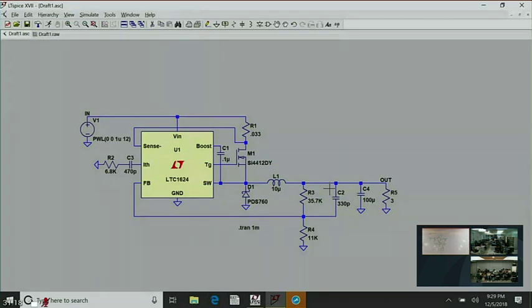Well, the feedback pin voltage is too low by a factor of 3. The output must be too low by a factor of 3. I bet it's shorted to ground. I'm going to go into short circuit protection mode. Seems sloppy. But the fact it works that way is a jolly good thing, because think about what the problem is with this output being shorted to ground.